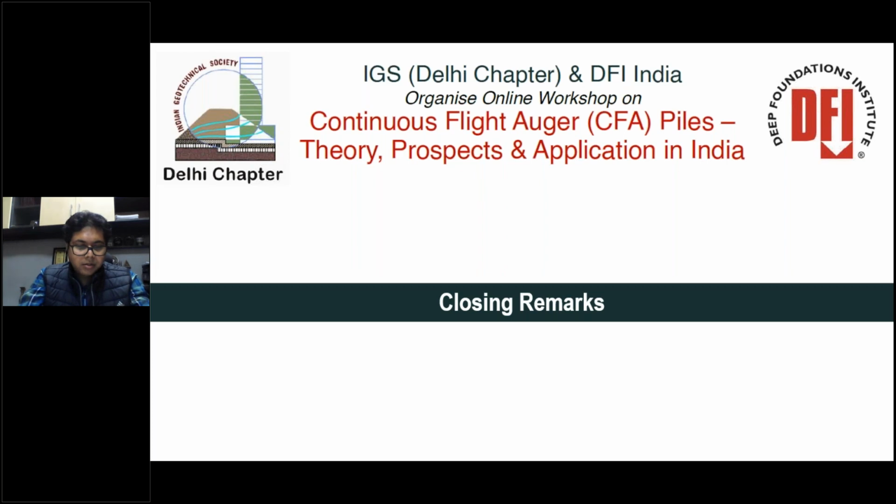First one on difficulties of alluvial soil and possible way forward by Professor J.T. Shahu from IIT Delhi. He presented about the bored cast in situ pile of 1.2 meter diameter constructed at Gautam Nagar, and he talked about the instrumented pile and different types of static and high strain dynamic tests. He also discussed the pile dynamic analyzer, PDA, and CAPWAP analysis, pile integrity testing, and the cross-hole sonic logging test. He also presented the different instrumentation used for the testing and the different interpretations out of the instrumented results.